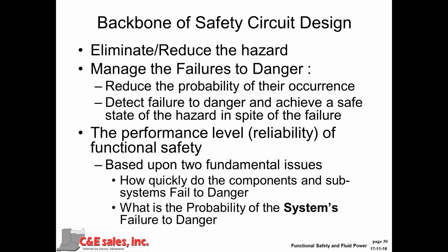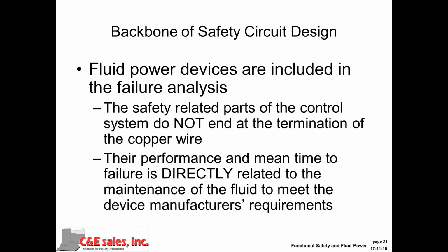So the performance level or the reliability of the safety function is based on two issues. One is how quickly in the application do the components and subsystems fail to danger, and what is the probability of, with that failure, that the entire system fails to danger. In some cases, it will definitely fail to danger. In other cases, it won't, and that's part of our design challenge.